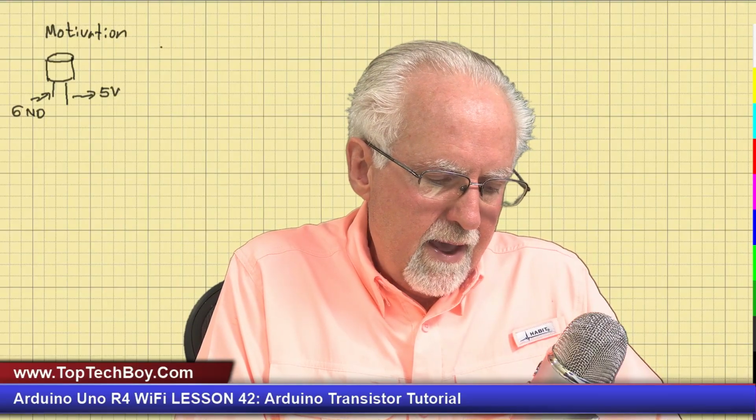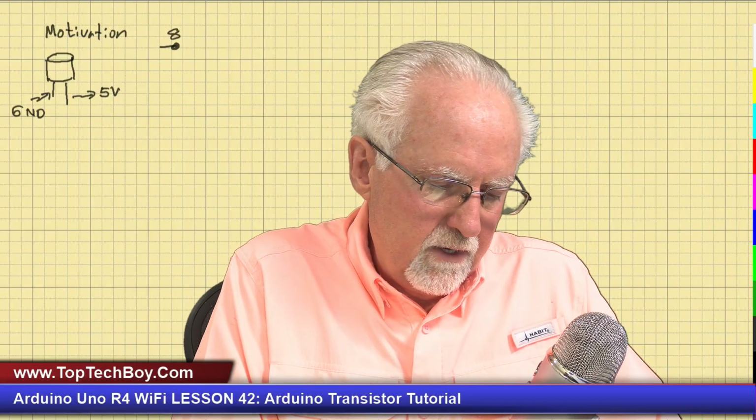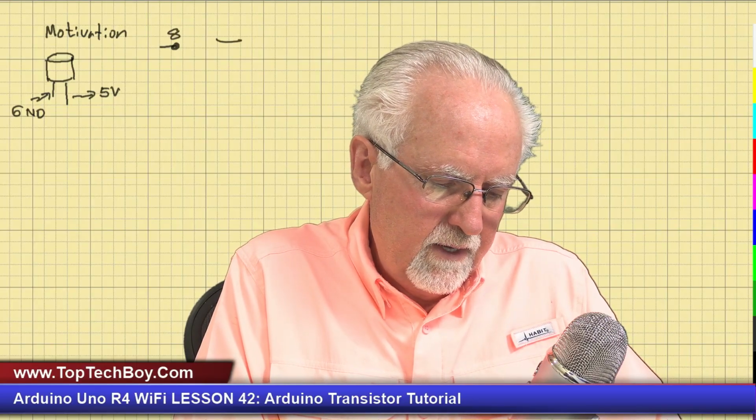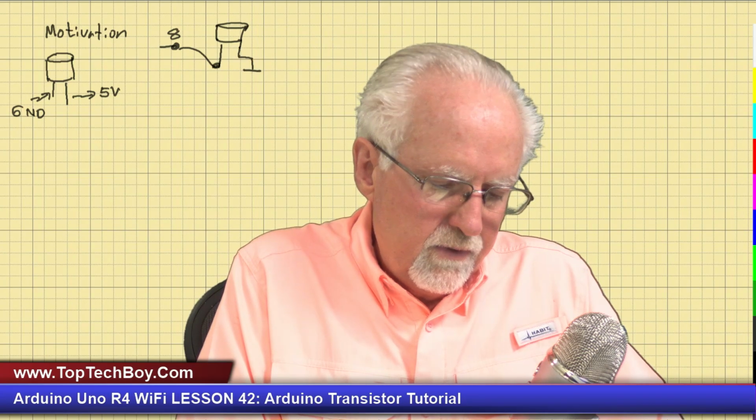Now, immediately you might start thinking, well, let's come out from the Arduino and grab pin 8 on the Arduino, and then let's connect that to the long leg. So connect pin 8 to the long leg of the buzzer, and then ground the short leg of the buzzer. And now if I turn pin 8 on or off, it would make the buzzer come on or off.